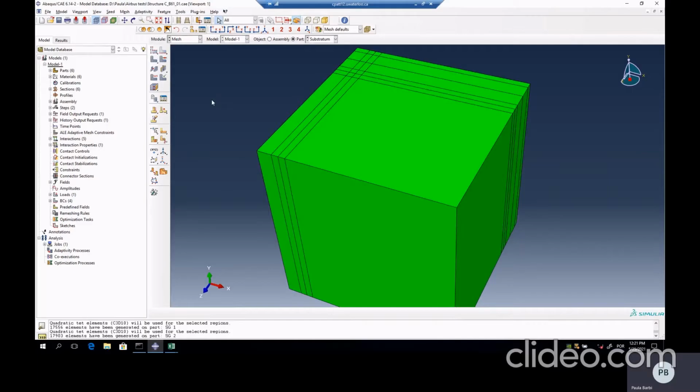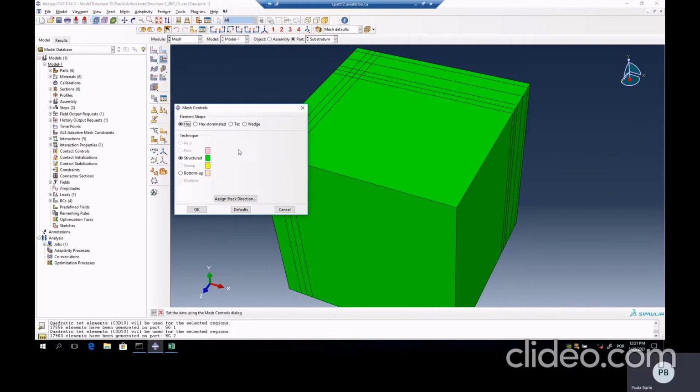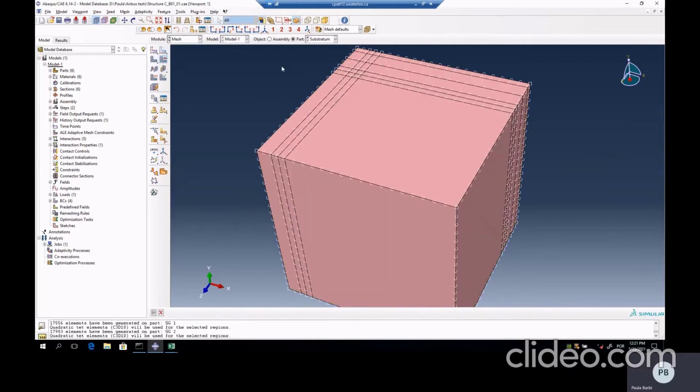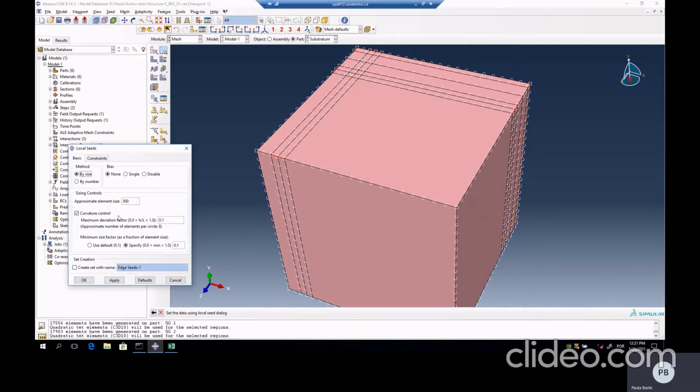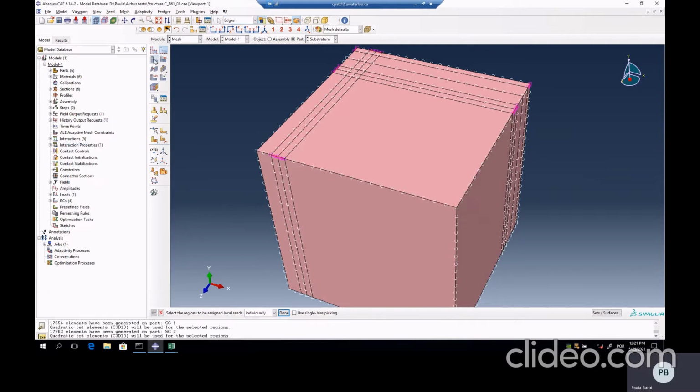Okay, so I'm almost done. Let's do it together for our last layer, which is our substratum. Select that, and then we're gonna mesh it. Load. Okay. And here we want the elements close to 50. And now we can mesh the part.